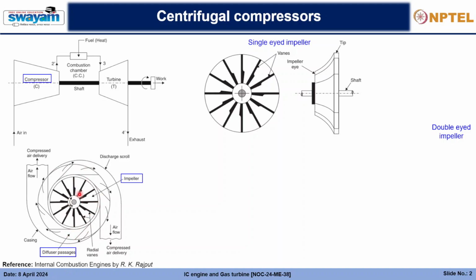They are not moving, and as the air enters the diffuser, the kinetic energy reduces, because the diffuser is not moving, hence it cannot impart kinetic energy. But as the air goes into this diffuser, the kinetic energy which is lost is used up in increasing the pressure energy. So higher pressure is achieved.